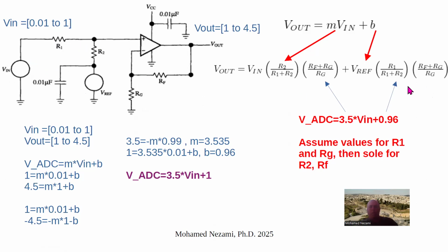So we see that, except VN in here really has a voltage divider because it's divided between these two. So that's what we would do here. It gets divided in here, and this one gets divided as well, except in this case, they're different. They're coming from different directions. The voltage divider that has to do with VREF, we multiply by R1 over R1 plus R2, this one here. But when we go to VN, we multiply R2 divided by R1 plus R2, which is this one here. And of course, we have the gain due to these two resistors. Let's keep this in mind.